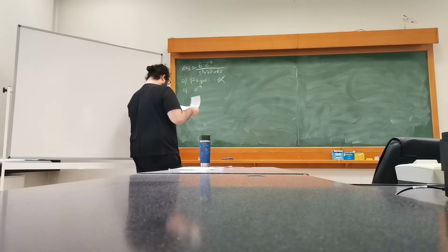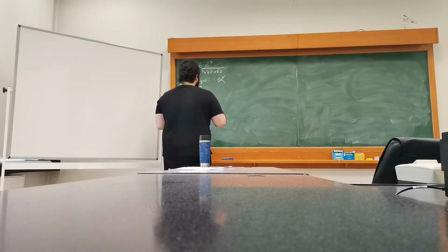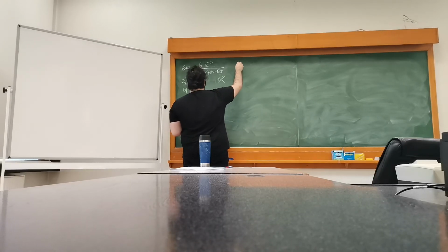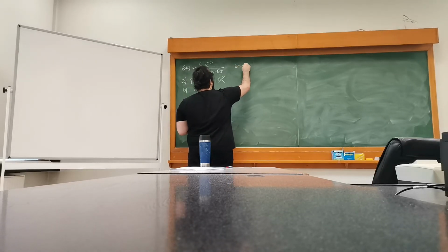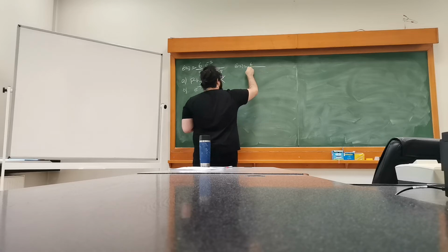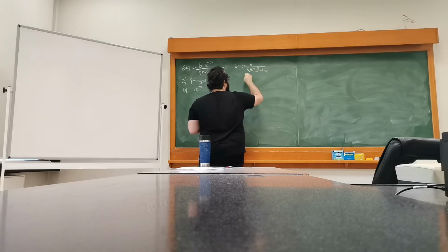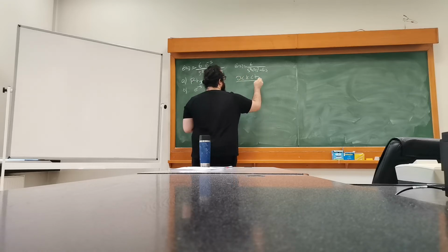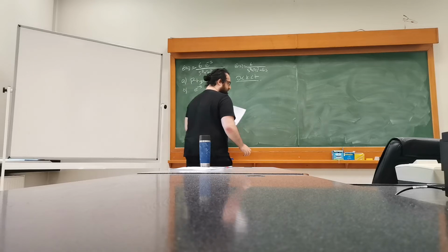So actually we've worked out what the stability interval of the system without delay is. Namely, it was G(s) = 6 divided by s cubed plus 7s squared plus 6s, and it was between 7 and 0. So that's the first part. Not really that exciting yet.